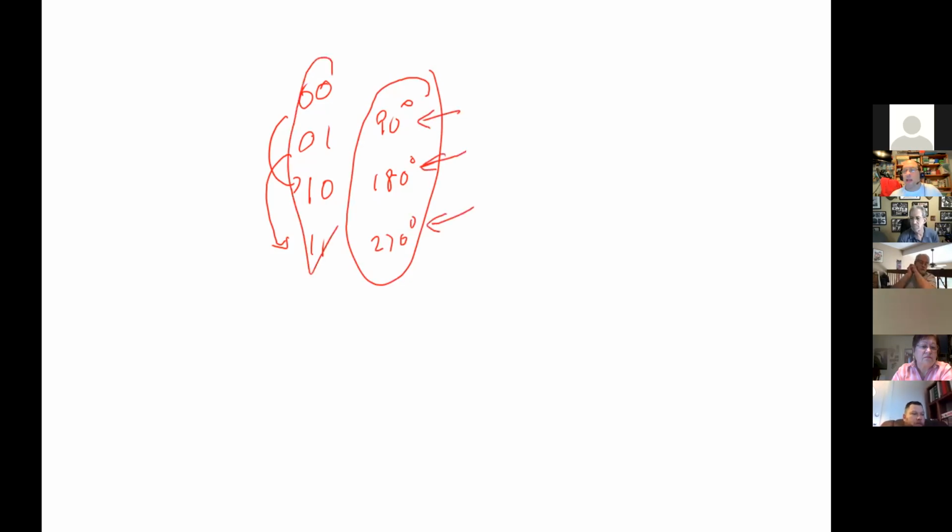I could come up with a coding scheme where the other station would see, oh, okay, I saw a phase shift and I was able to tell what the shift was. So I could actually say that, oh, it was a 90-degree shift. It was a change from a 0, 0 to a 0, 1. 2 bits at a time, for instance. So it just allows you to transmit potentially more data.